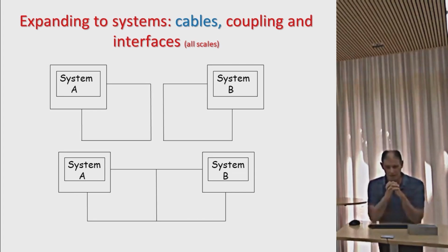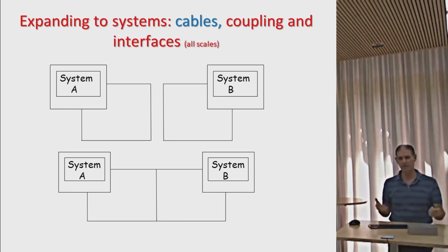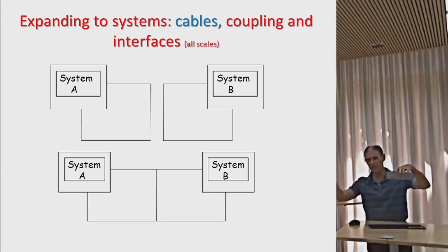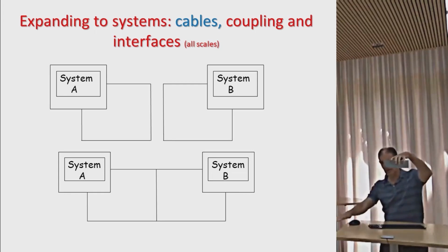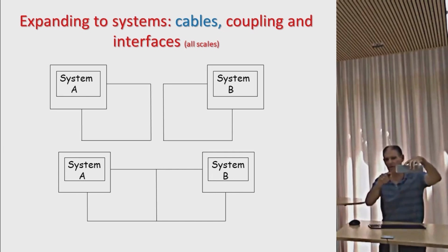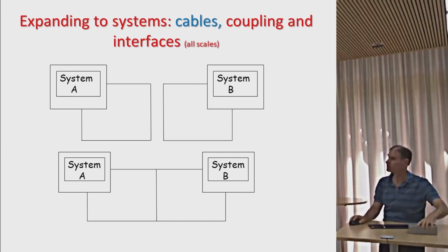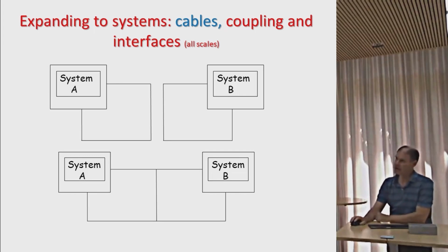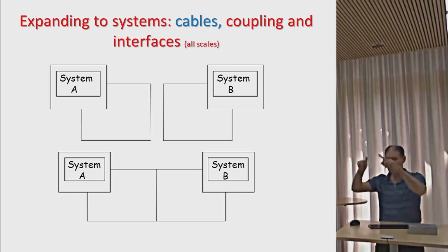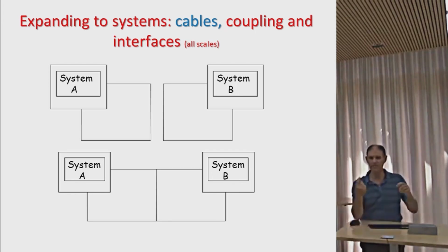Much more significantly in EMC is talking about systems which are connected by cables. What I would demonstrate through experiments or through more detailed material is that the moment you connect a cable to a system, that cable going down to ground, coming back via some undefined earth path, connecting back to the system, those current paths are determined by the shapes of your cables. And if, for example, I've got a system A, which is quite a big system, and nearby I've got another system with cables on it, those two loops will cause interference coupling between them.